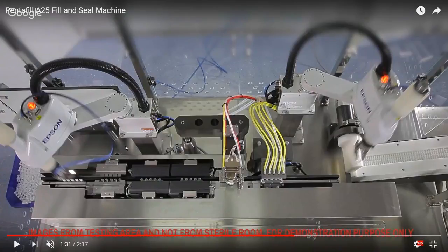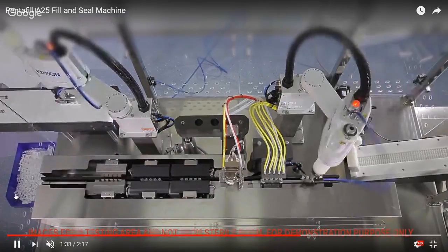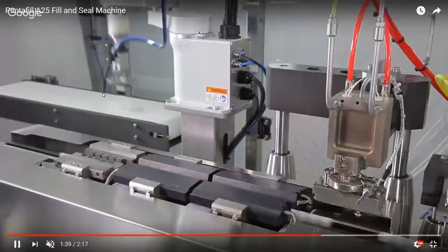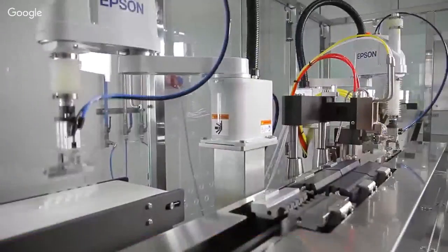You then have two sealing stations, two hot crimp stations that basically perform the same operation, but we make sure in this way that the plastic is melted. Then we have a cold crimp. You see the blue piping; they bring the chilled water. This station basically does two things. The first thing is it gives a shape to the seal. And the second thing is it cools down the temperature of the plastic, so that from the next station, when the filled strip of 5 vials is taken by the pick and place and is placed on the conveyor, the strip is already at room temperature.